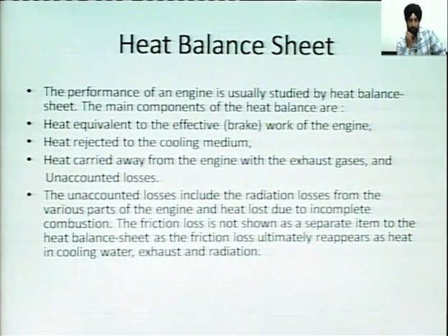The amount of useful heat supplied can be calculated by taking into account the brake horsepower. So first of all, in order to prepare the heat balance sheet, we have to calculate all of the heats going to various parts. Suppose what fraction is converted into useful work, what fraction is taken over by the cooling water, then what fraction goes along with the exhaust gases, and then radiation loss.